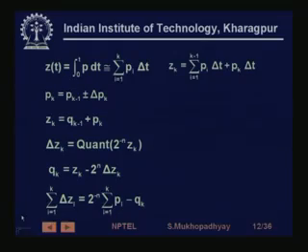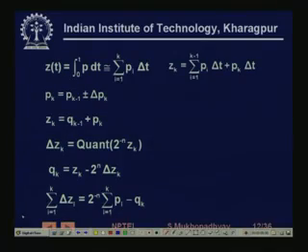So it is not that every time we are going to send a multi-bit number. We go on adding a number to an integrator, and when this sum becomes larger than a certain quantity, then we give one command to the machine that you now make one motion along this axis, right. Mathematically speaking, this is very simple: we want to integrate a certain number p.